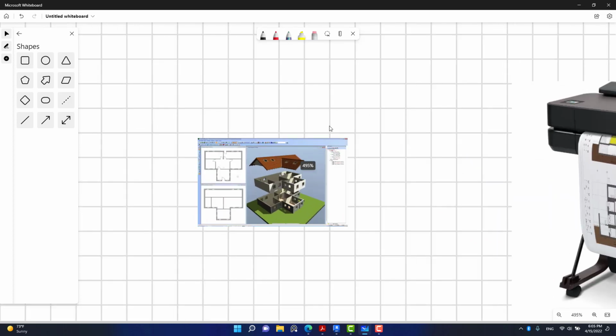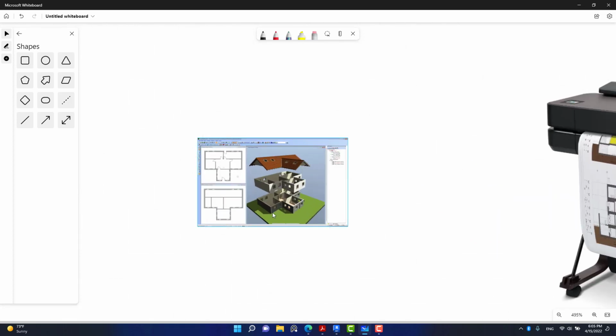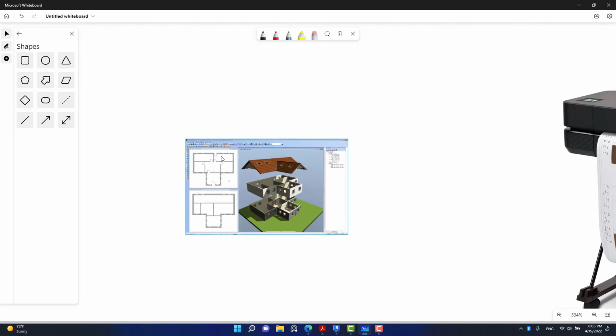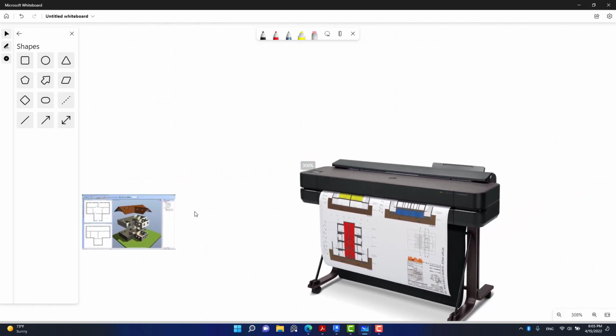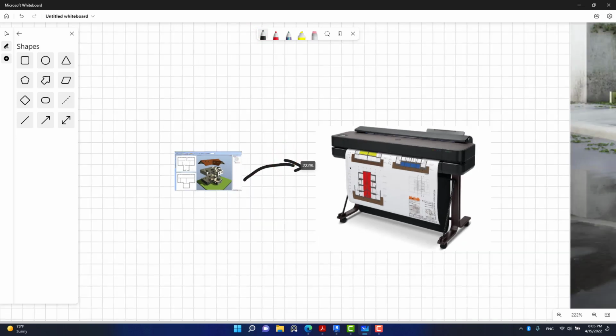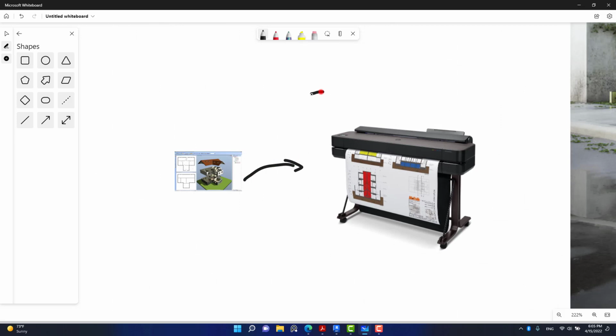Okay, for example, this is Revit. It's not Revit, but accept that it's Revit. This is Revit, and you are trying to plan the house like this, and this is your screen. Okay, let's accept that this is your screen, and you want to print it. You will go to printing. You'll say, print this one out, but the man will say, in which scale, please? Okay, he will ask you in which scale. So if you don't know the scale, it will be a disaster.